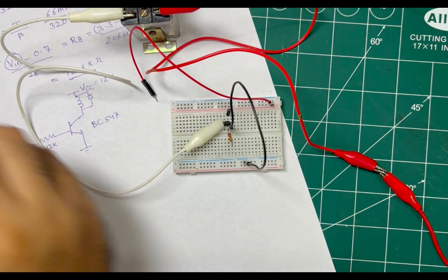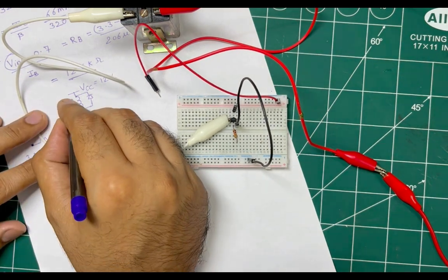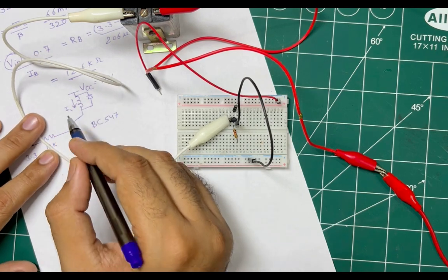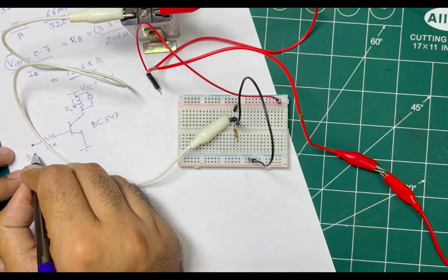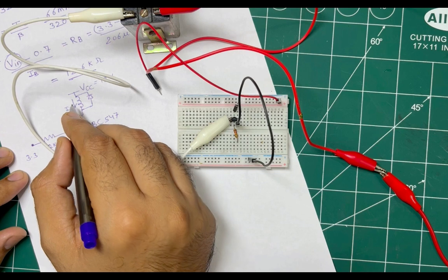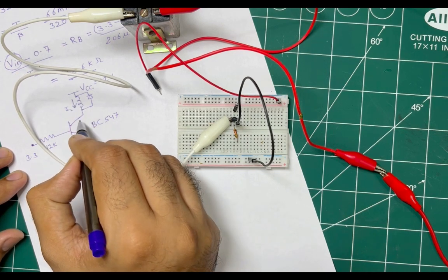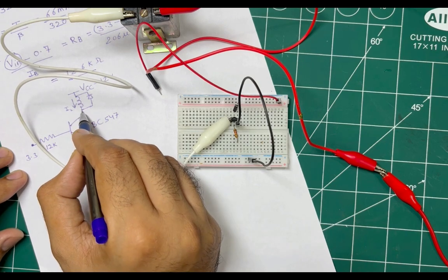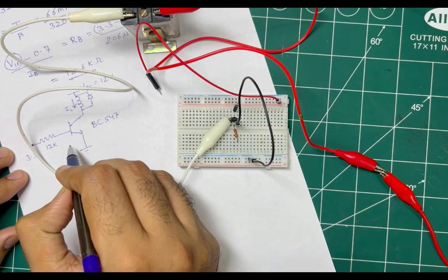The purpose of this freewheeling diode is that whenever the relay is turned on, the current will be flowing in this direction. A relay is basically an inductor. So when the supply of current is stopped, let's say because the transistor turns off, this current cannot immediately die. It needs some path to continue flowing. If you break that path, it will result in a buildup of a very high voltage across the relay terminal, which can then damage this transistor.